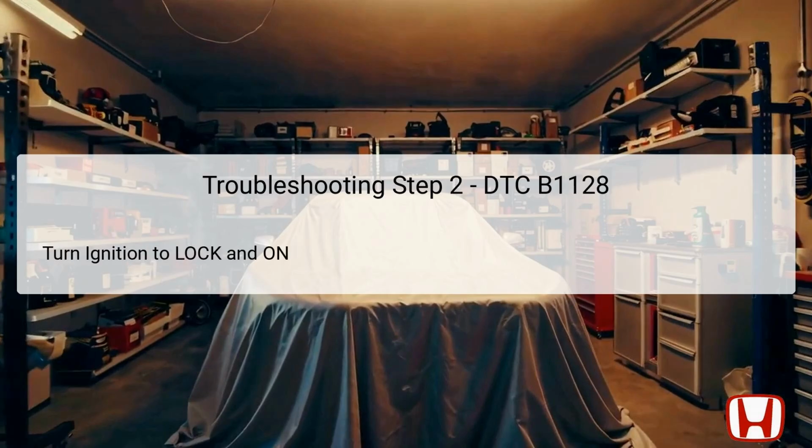Next, turn the ignition switch to the lock position and then back to the on position. This action resets the vehicle's electrical systems and prepares the vehicle for testing the driver's door lock switch. The ignition state directly affects the operations of many electrical components in the Honda Civic, including the door lock system. Ensuring the ignition is cycled correctly helps in re-establishing communication with the vehicle's control modules. After performing this step, you can better assess the response of the door lock switch during subsequent operations, which can be vital for determining the fault's persistence or its resolution.